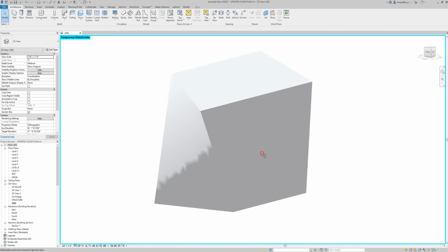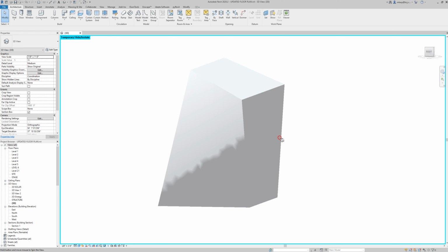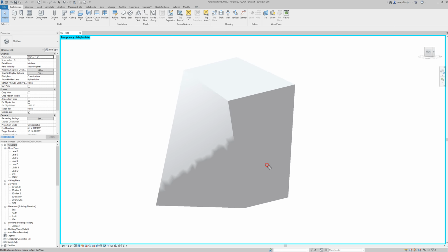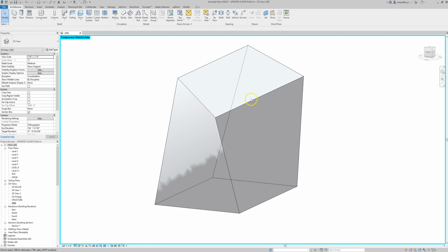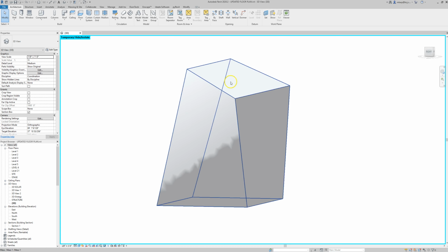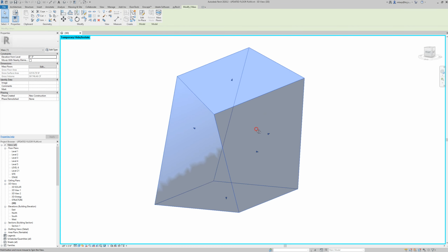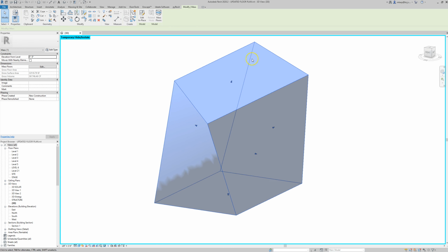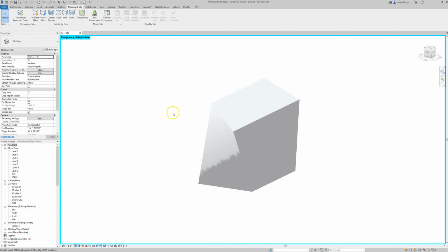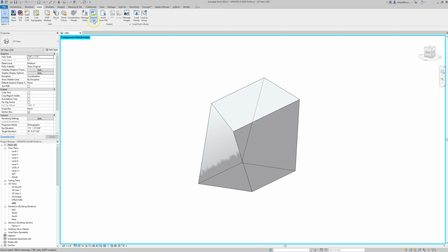When dealing with sloped walls in Revit, you typically have to make the wall a wall by face and make it off of a mass. So you can either make a mass inside of Revit using your massing in-site and mass in place tools, or, instead of importing CAD, when you bring in a